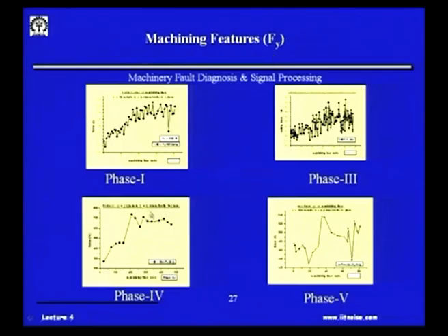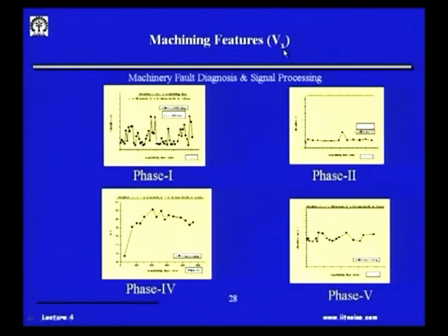Similarly for Fy, prediction in the laboratory and then prediction in the industry. Similarly for the vibration in the x direction, we have again machining time, because once we know that the levels are higher or not allowable, then we can also predict the remaining machining time by which this cutting tool has to be replaced.